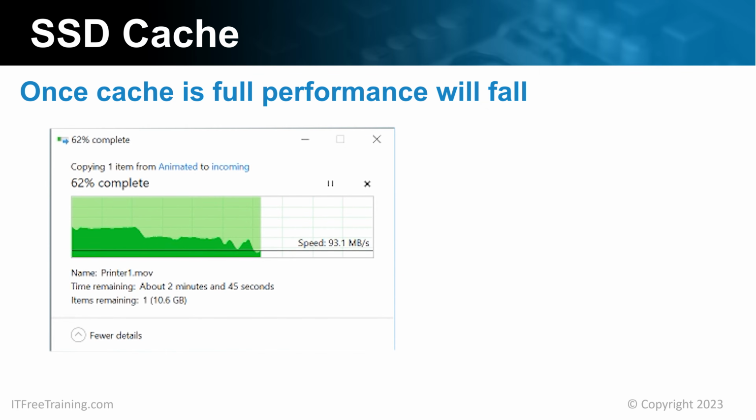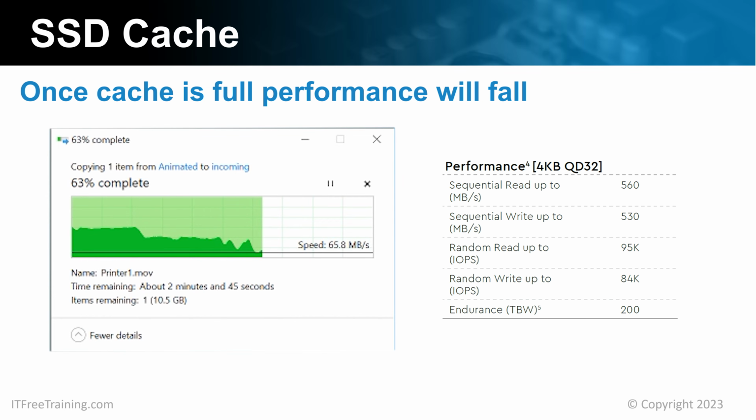When purchasing a solid-state drive, these are performance factors to consider. The specification of the solid-state drive may include performance specifications like the ones shown. You will notice the maximum write speed for sequential writing is listed as 530 megabytes per second. The best we achieved was 400 megabytes per second.